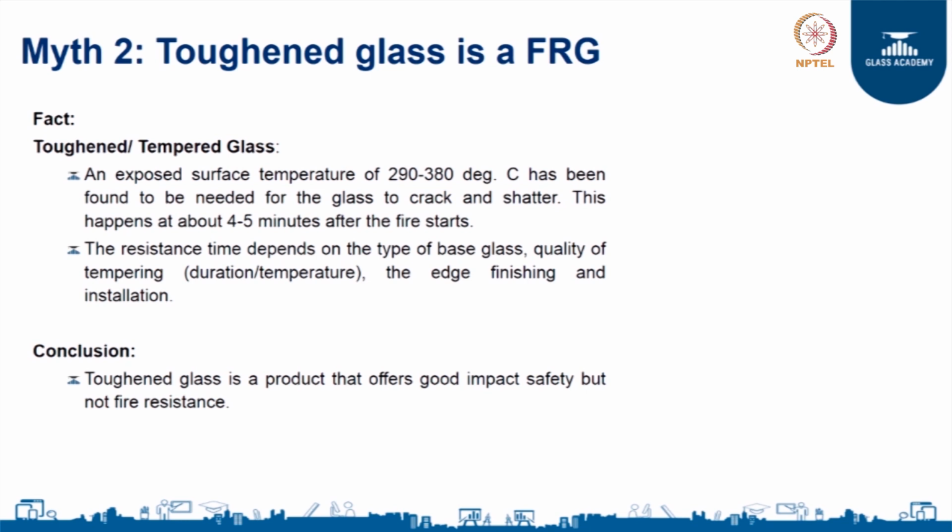The other myth is that a typical toughened or tempered glass can also be used as a fire resistant glass, which is not the case, because a tempered glass can only withstand a maximum temperature of 380 degrees C. During a typical fire we observe that the temperatures can go up to 1200 degrees Celsius. So, the tempered glass would typically break 4 to 5 minutes into the initiation of a fire, and